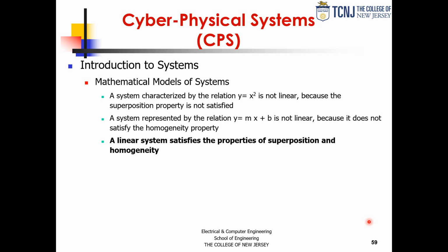And we see offsets in all kinds of circuits. You can get rid of an offset if it's in the numerator, okay? So remember that. You can get rid of offsets if they are in the numerator of whatever expression you have. If they are in the denominator, then they're not only an offset that makes the system nonlinear, but they are very difficult to null out, okay?